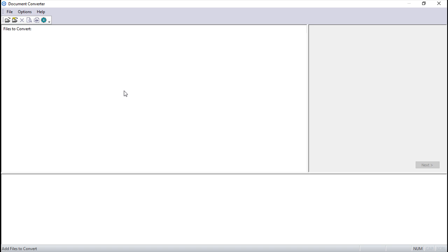You can also try, in some particular cases, if you have some models or some 2Ds, to pass them through STEP format or another format to clean the file and then import it. You know that you will lose information from parameterization and so on that you may have inside. It depends on the situation. For now, just brief information that you have these available.